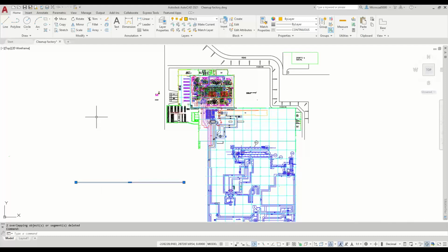Now, again, you may or may not be aware that overlapping segments on a polyline can give you problems when you are hatching. So not only does it resolve the issue with the polyline, giving the incorrect length, but it also may well resolve issues with hatching as well, where you are picking an object to hatch in because you've got a weird boundary on it. So yeah, watch out for that one. So the overkill command, dead useful tool there. And this file size is coming down all the time, coming down, coming down.